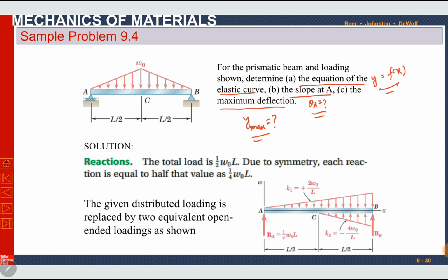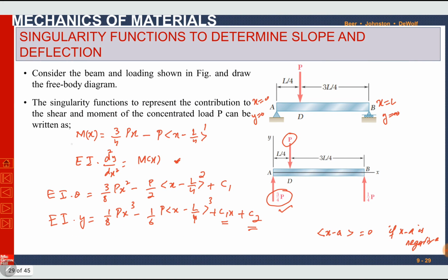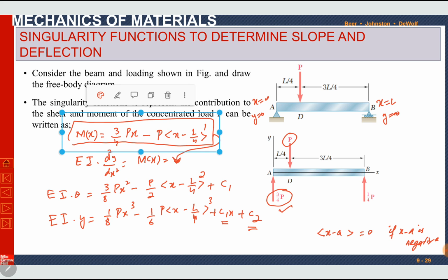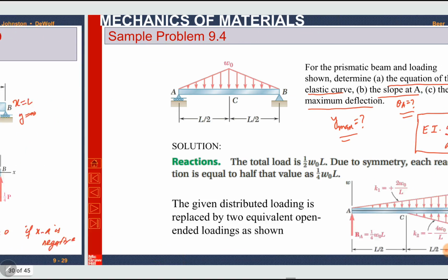So we need to find these three things. First, to find the expression of y, we need the expression of moment, so that we can integrate it twice to find y. We will find the expression of moment using the singularity method, using singularity tables.